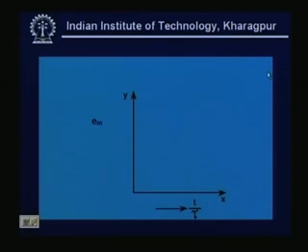On the x axis we have plotted t by tau instead of t. It does not matter because it is normalized, and t is just multiplied by a constant factor of 1 by tau. You can see here that at a very low value of t by tau, when it is 0, the initial state where we have just given the step input, my output error is maximum. As time grows, the error will fall down.